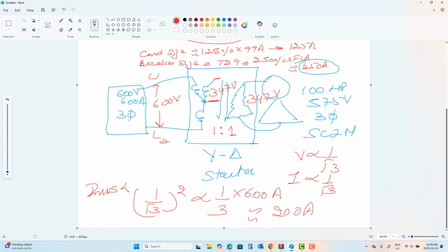You always start a motor at a lower voltage, which is called low voltage starting. One method of low voltage starting is a Y delta starter. You could even use reduced voltage starting by adding some resistors to it as well. More resistance, less current means less inrush. That's another way of doing it. But the most popular one for three phase is the Y delta starter.